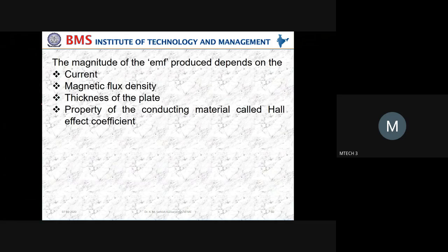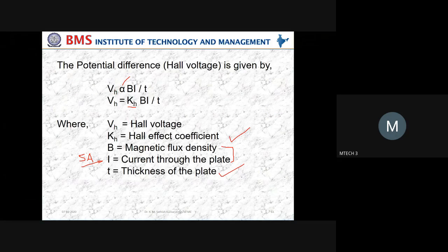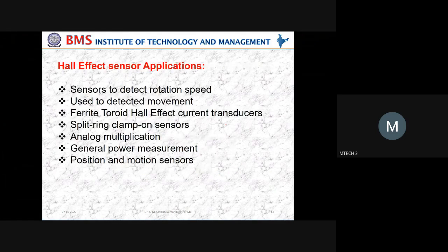You can observe clearly that the magnitude of the EMF produced depends upon, number one, the current passing through the conducting material. Next is the magnetic flux density. Next is the thickness of the plate, and then the property of the conducting material called the Hall effect coefficient. Now if you go with the equation, V is proportional to...